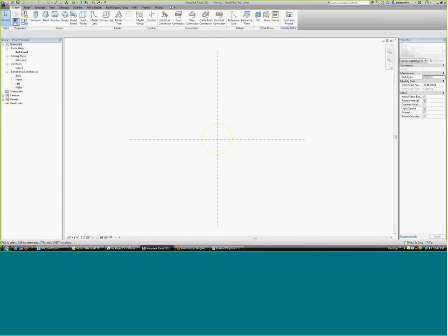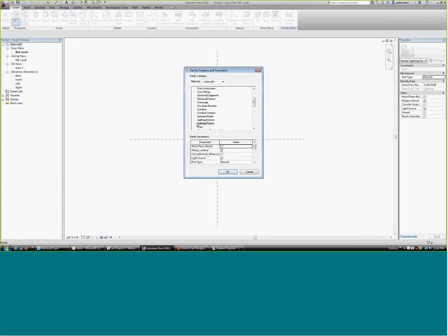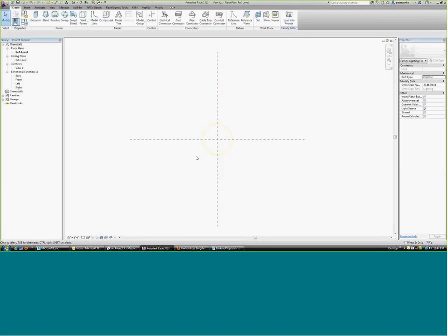One of the problems with a lot of these light fixtures to begin with is that they're told to always be vertical, and that's really tough. And as you've noticed, you can't really rotate them out of axis, which is hard. With these non-hosted ones, we always uncheck always vertical. We'll allow it to differ a little bit. For instance, like our strip light fixture family, you can't turn it over,